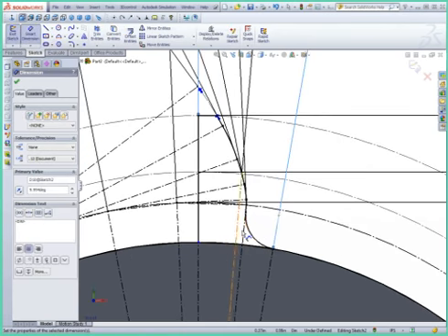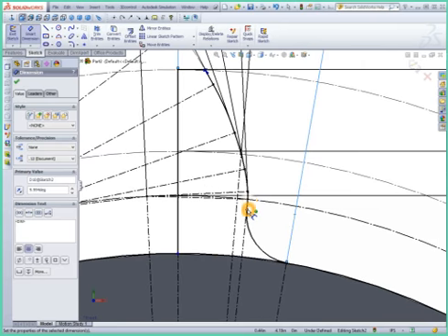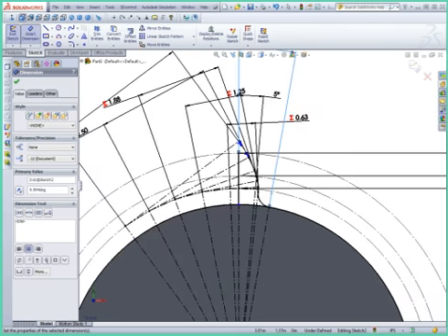And so now we have a pretty heavy radius on here, but the nice thing is as long as there's a little bit of space between here and there, we'll have plenty of clearance on the tip of our tooth. So this entire sketch is complete. We just need to remove the rest of this line to be able to extrude it.